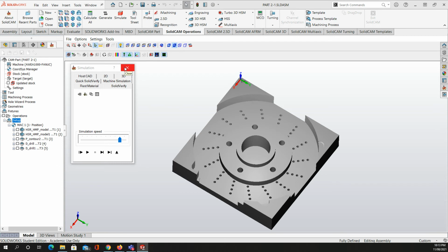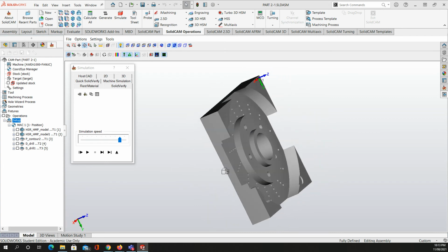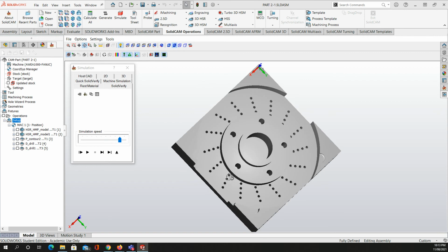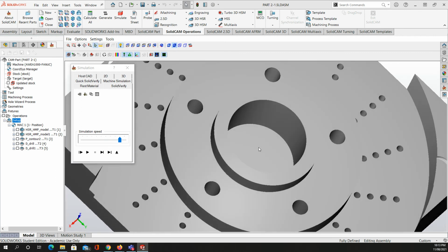Anyway, as I told you, we can set that later by getting the G00 to go to a higher level, then moving to the end. Okay, now, oh yeah, because remember, we had 2 extra millimeters from the other side, and that's why it didn't go all the way down on this side. Okay, now I'm going to do the profile cutting.